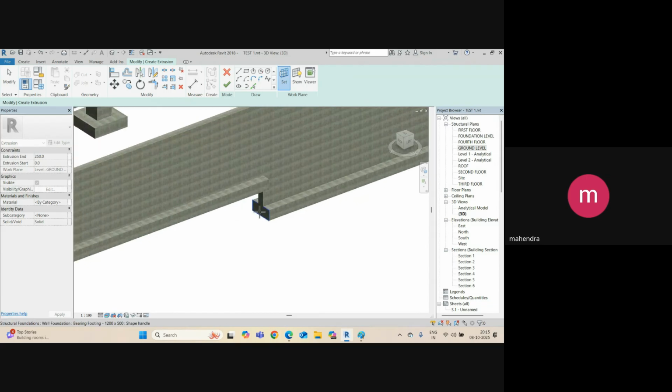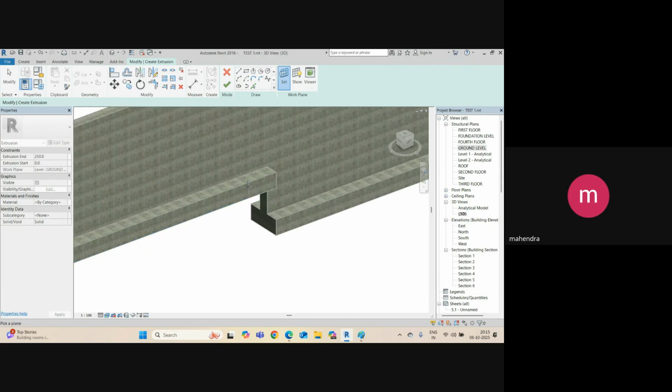My shape is extruded in this direction. So I will use Pick a Plane, meaning my shape is parallel to this shape. Once you move your cursor, this shape is selected, then this shape is selected, then top, side, bottom also get selected. But I want to select this one, the left side. So I will select this. Okay, so you are ready to create your shape now.